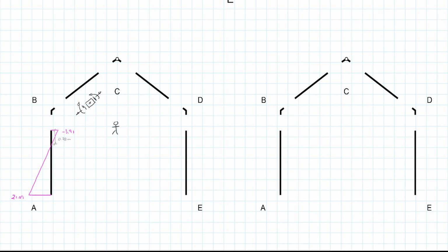So we're going to keep working our way around the thing. So we're at member BC. This is where we have to look at the normal and the shear force values in local coordinates, because we need the normal or the parallel to the cross section. And so what we have here in shear at B, we have 8.6 down, which would be negative for us, right? Now we're on the negative face, it's going down. So that's a negative of 8.6. So I'll just draw that down, negative 8.6.